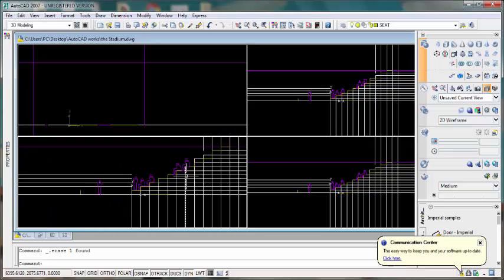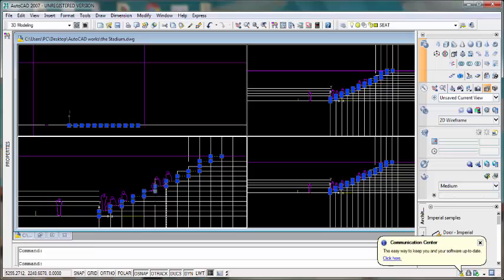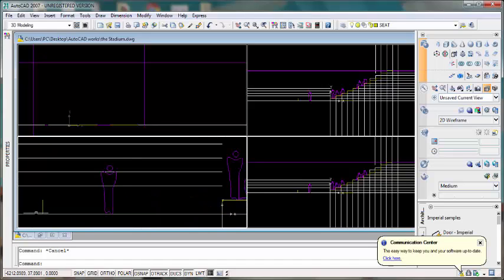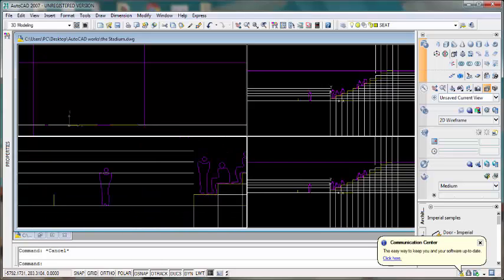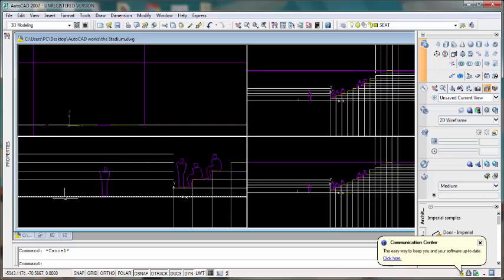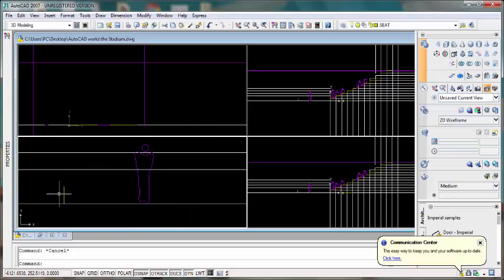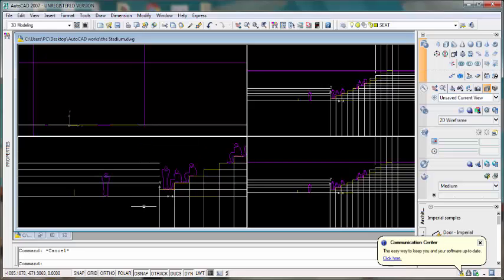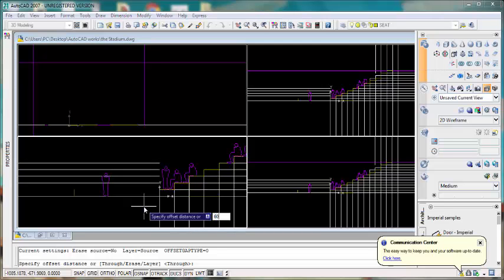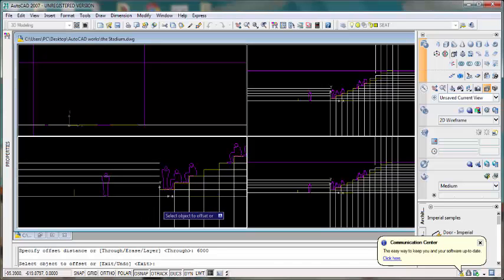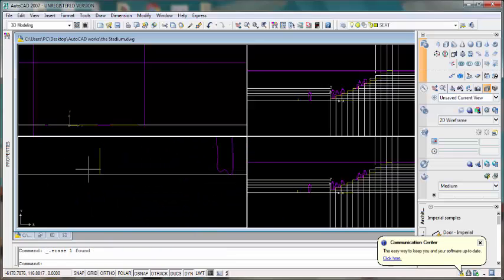So this polyline that you're seeing is an indication of our arena, just as it will be. Now, to use the Revolve tool, I also want to indicate the radius about which these people sitting down will take. Okay, and that is where I put this line. Now, to show you how I did the line, I just offset, I think I did 6,000 millimeters. Yes, that brings us to this place. So that is this line you're looking at.